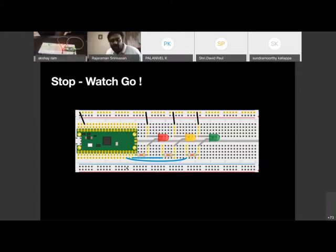The Pico. So the jumper cable and the resistor, in essence, is equivalent to connecting this LED to this port of the Pico. So it doesn't matter where you put these, so long as the lines are taken care of and the jumper cables are placed in the right places where the resistors are connected. Okay. Then you can program this port. You can turn on this port. If you turn on this port, then this port is connected to this green, so this will glow. If you turn on this port, then this is connected to the amber and this amber will glow. That's the essence of it.